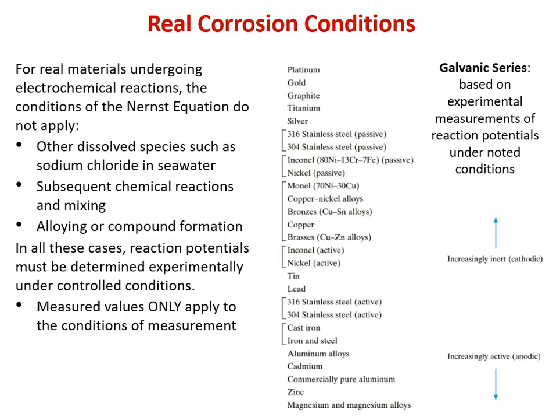It forms a very tight, adherent, thin oxide that literally insulates it electrically and prevents the titanium metal from interacting with solution. Silver's noble, and then we get into a series of our copper and nickel and stainless ferrous alloys, all of which are essentially noble in practice, not because they're electronegative, but again because they form very adherent, effective passive films.